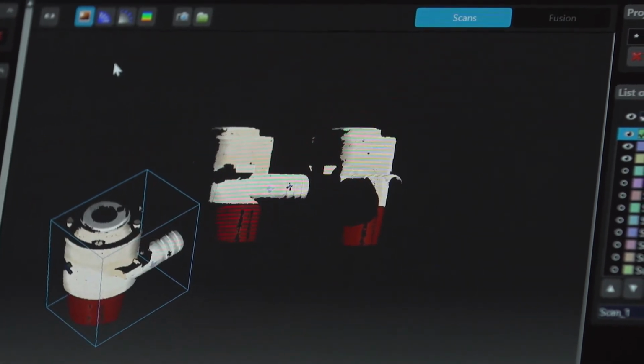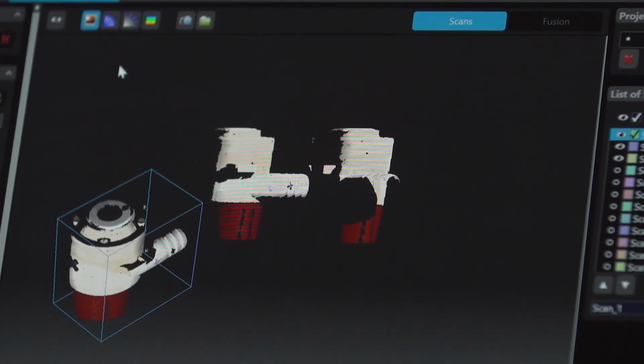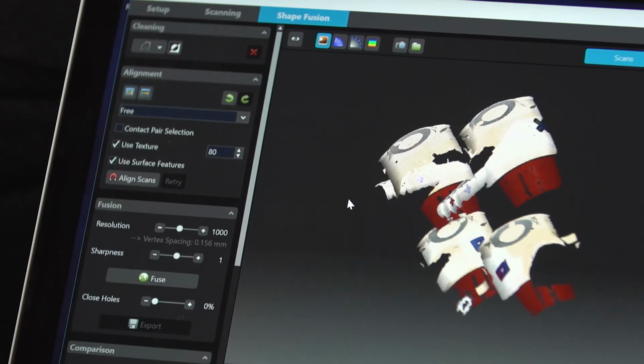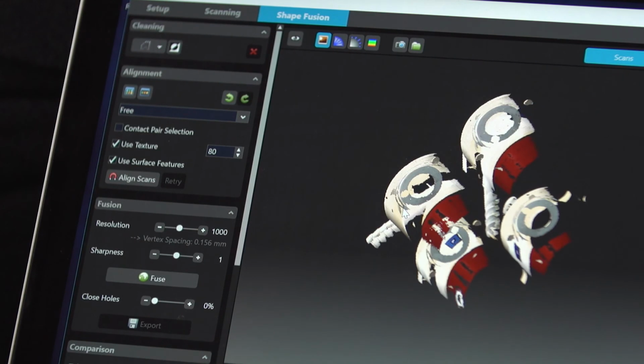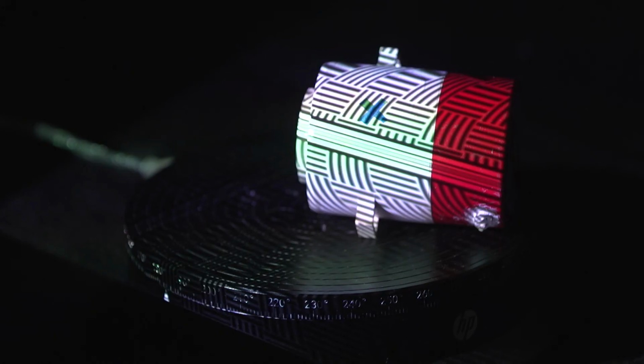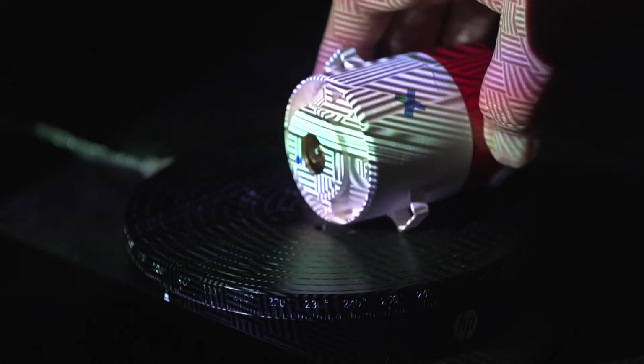Use the 3D viewer. Review the scan results and determine where additional scans are needed. When objects are complex, or when additional scans are needed to capture areas of the object that were hidden from view, such as the underside, it may be necessary to perform additional manual scans. The cleaning and aligning of these manual scans will be addressed in Tutorial 3.